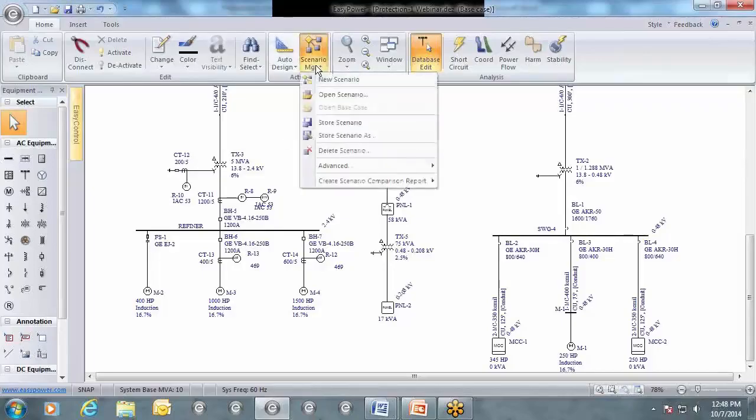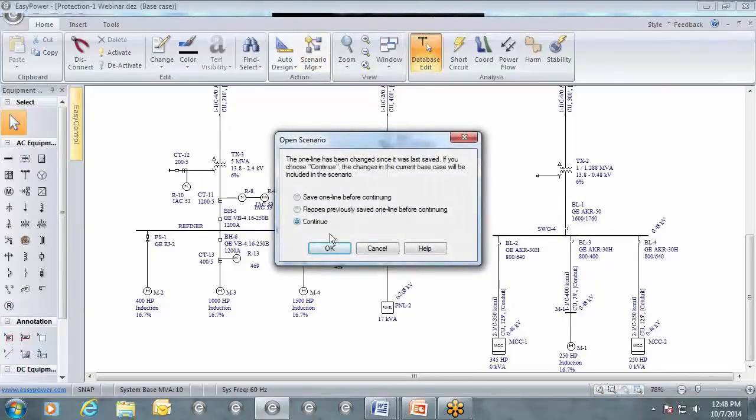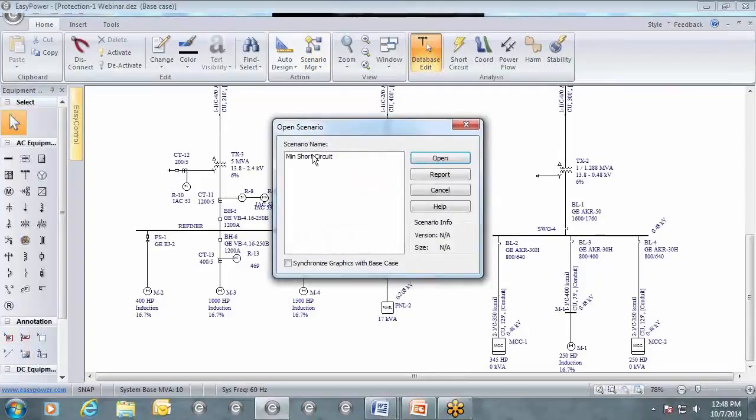couple more things to discuss. One is in this sample, we have a scenario. So one of the conditions that you may get is a utility gives you multiple fault currents. So it might be wise to run both cases and see what the most conservative incident energy is.